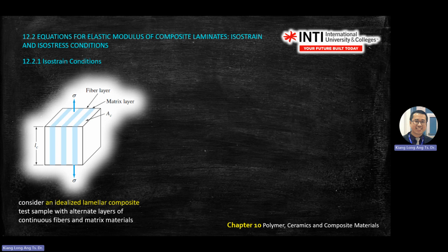So this is a laminar composite. We want to find the stress on the material that causes uniform strain of all the composite material, because this one, you layer like this and you pull on this surface. So all these will have the same deformation. You will pull in this direction.